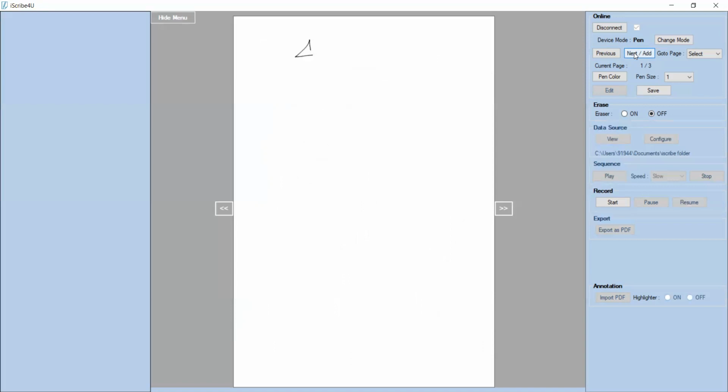What is this right angle relationship which we have discussed in the last class? If this is theta, then this is 1 minus zeta square, this is zeta, and this is 1. So cos theta I can write as zeta, and sin theta I can write as square root of 1 minus zeta square. So this is the relationship that exists between zeta and theta.